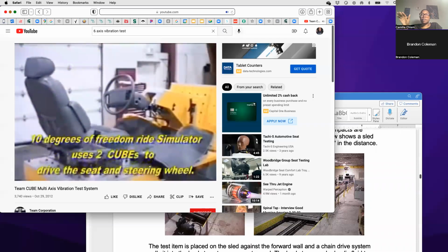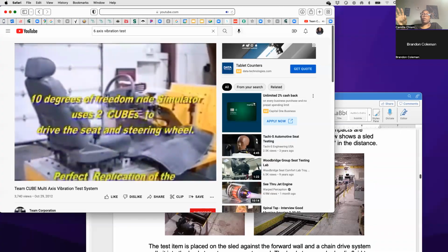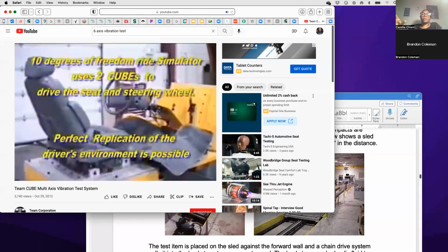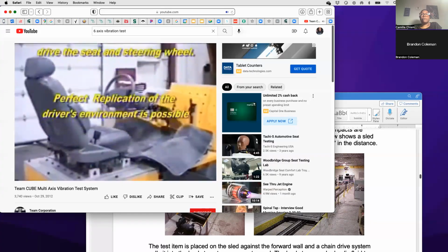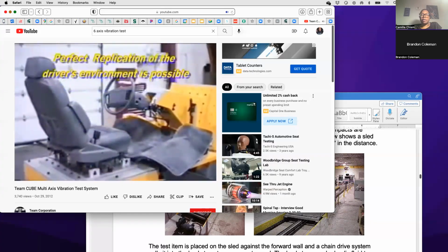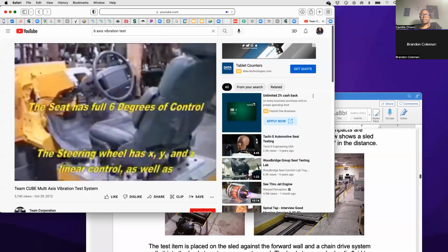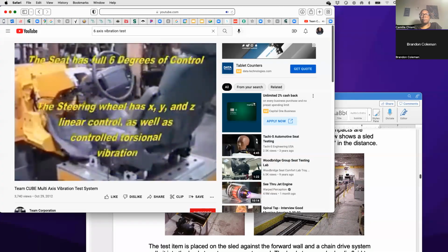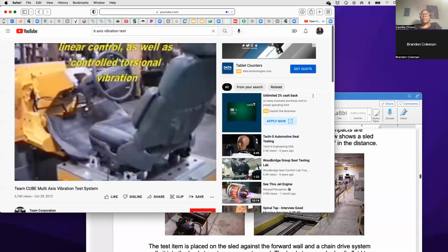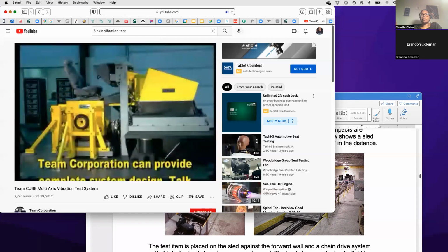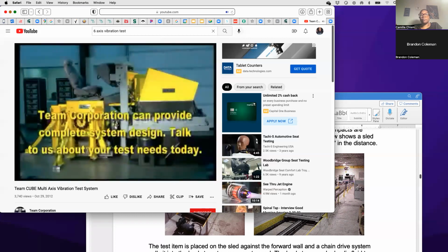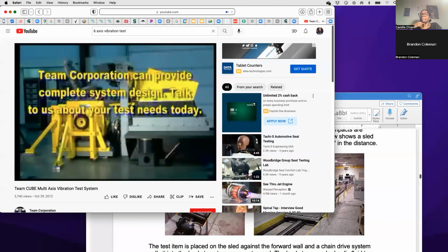So when I talked about the conditioning, you could actually put your large parts in a chamber like this for whatever period of time is deemed in your requirements for the test to condition it ahead of time. And then you can run that test in that same area or room that's conditioned to the specified amount, which would be 72 degrees and 50% relative humidity.